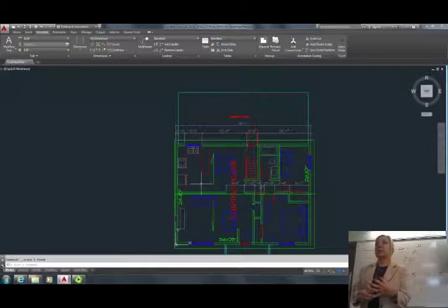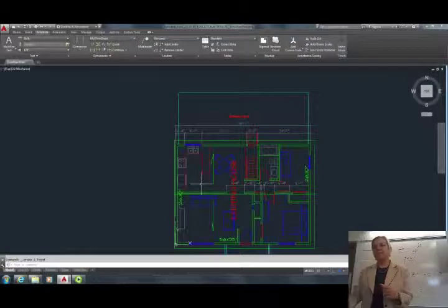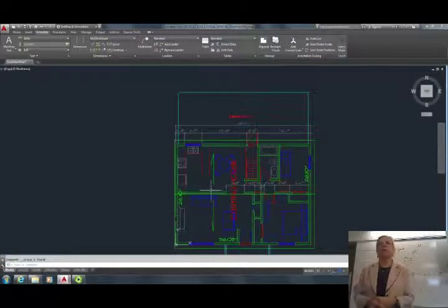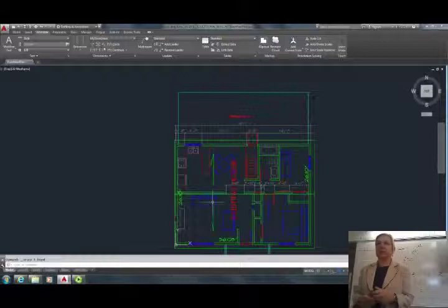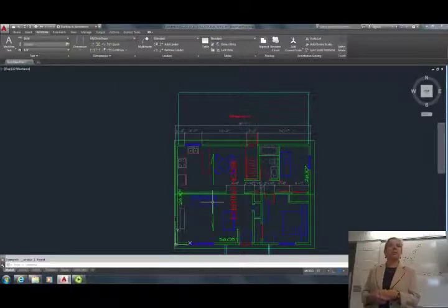But in a nutshell, how many strings, horizontal strings? The students ask me, how many strings? Well, as many strings as you need to have the contractor build all the walls that you need. But to simplify the drawing, I would not be dimensioning the walls. I would just have a general note saying all walls to be 4 inch with half-inch drywall both sides.